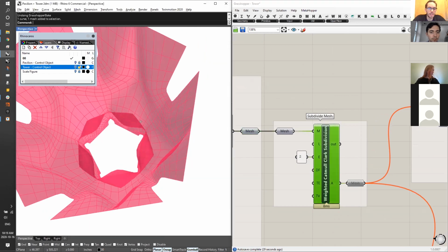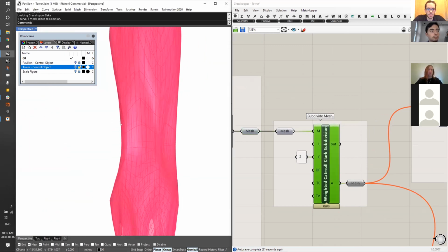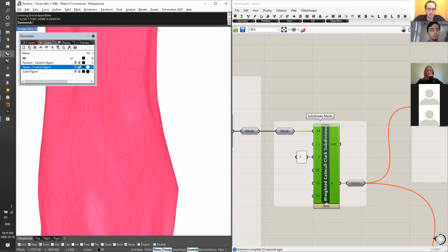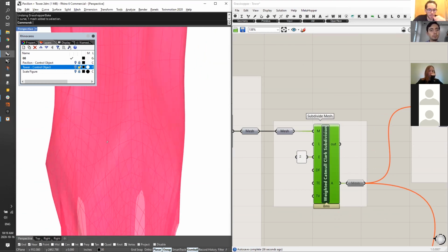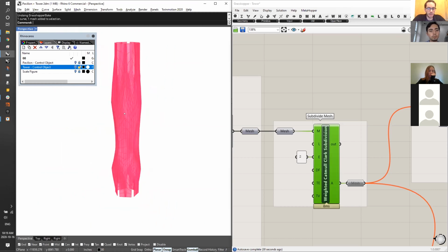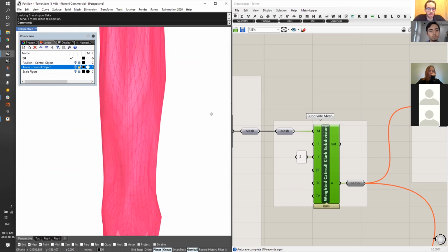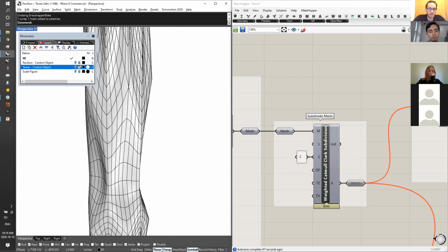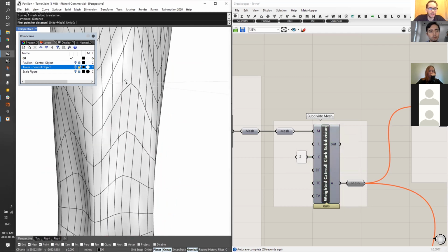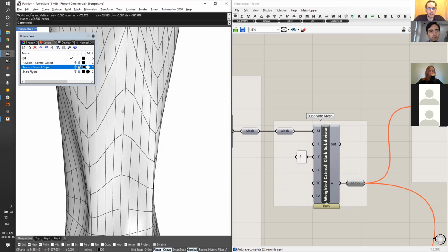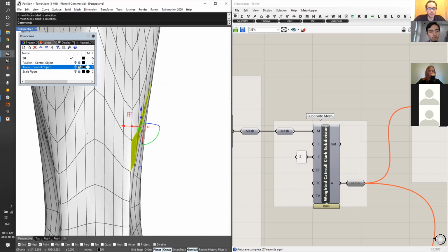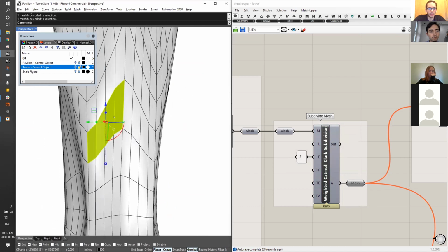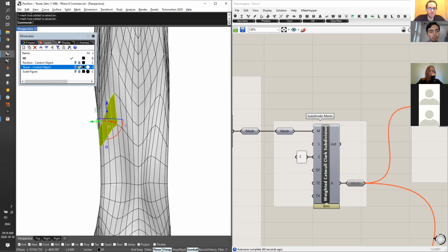Now it got subdivided and got smooth because of aesthetic choices, but also because I'm looking for more faces, trying to get more series of panels and trying to discover how many panels I can get from the initial mesh topology. Arguably, you could take this particular object and say you measure this out and this happens to be way too long for some fabrication reason. You can take these couple edges or these couple faces, or sort of topological band, and then look at subdividing that in one specific direction.